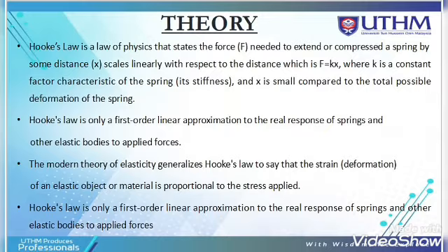Hooke's law is only a first-order linear approximation to the real response of springs and other elastic bodies to applied force. The modern theory of elasticity generalized Hooke's law to say that the strain (deformation) of an elastic object or material is proportional to the stress applied.